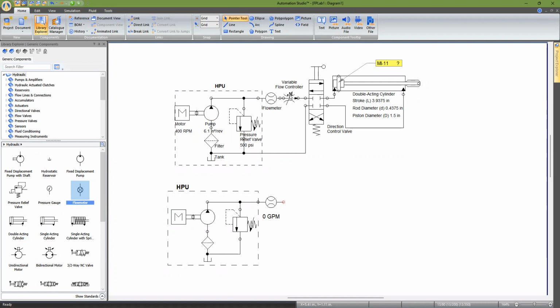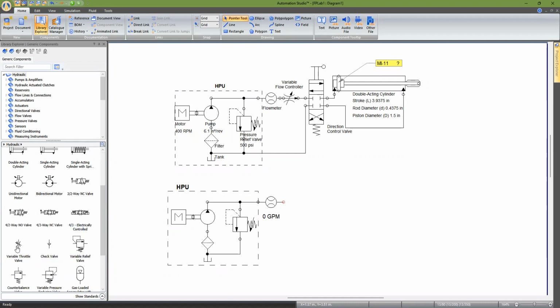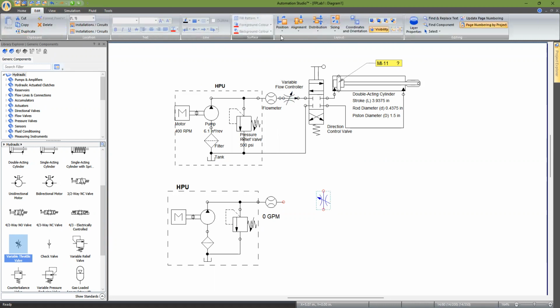Now we finish the connection by bringing a needle valve here, a flow control valve. So if you look in the home page, there's our needle valve. But you see there's a slight difference in these two. This one looks like it has an additional arrow here. This one, even if I turn it, let's say I turn it clockwise, now they're more similarly aligned. Now this line has an arrow here, this one does not. And it means something is different between these two.